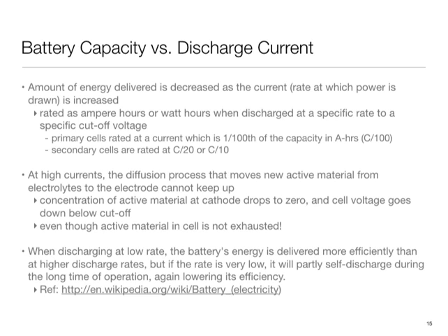So the story is that not all battery chemistries manifest this effect to an equal extent. For example, you would see this a lot in NiCad or nickel metal hydride. You won't see it to the same extent in lithium ion. That's one. It also depends upon what the current was to begin with, relative to the battery's capacity. This effect will be more dominant if your current was in the range of the battery's rated capacity, as opposed to being a very tiny amount of current. In other words, duty cycling a tiny amount of current is not going to help that much.